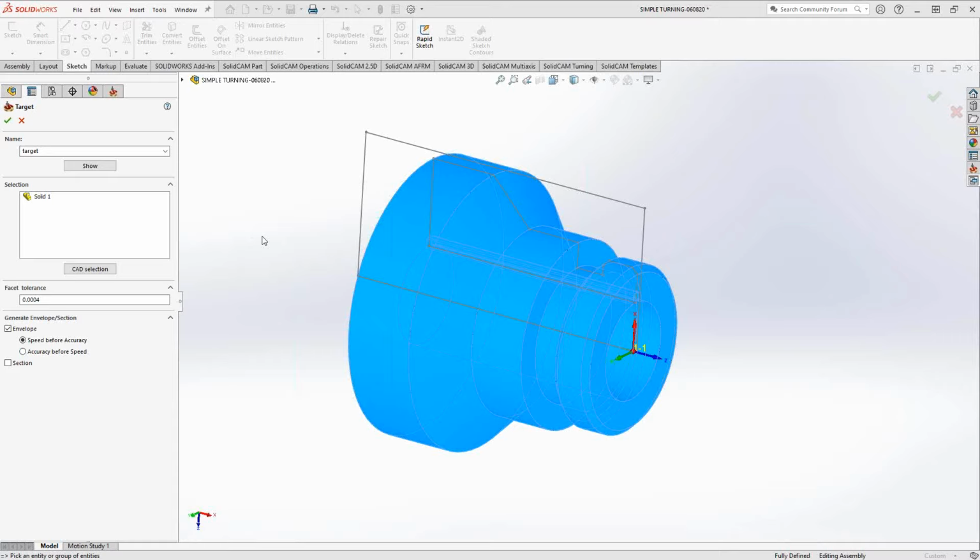It meshes with the upper half of the target and the solid and your stock definition, so you can generally get started with that. But if in the case you need some lower geometry, maybe you're doing some turning on the lower half, you want to see top and bottom different pieces of geometry, or maybe there's something about your solid that still doesn't work with the envelope option, and you want to just get a direct cross section of your part. That is what that section option will do.